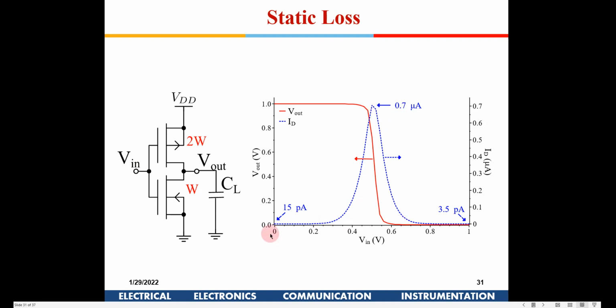Okay, there will be several other factors which we will see in the next class, but this static current will be the same, because it is stabilized. So the currents we observe in DC analysis will be the same currents you will see in the transient analysis also, when the input is not changing with respect to time.